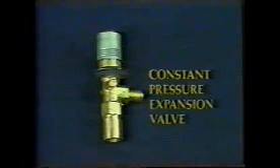It's also called a constant pressure expansion valve, since it maintains a constant pressure in the evaporator regardless of the load on the system. It's actually a reverse-acting pressure-reducing valve. The automatic expansion valve operates by means of a diaphragm or bellows and a spring. This one has a diaphragm. It's activated by the pressure in the evaporator, which pushes against the bottom of the diaphragm. The spring exerts a force on the top of the diaphragm.